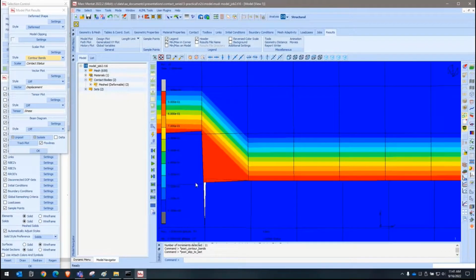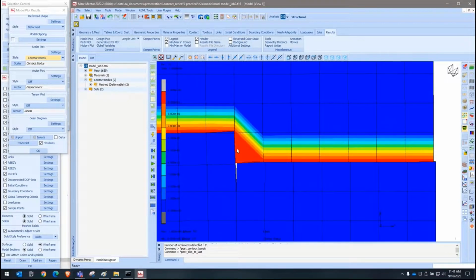The argument is this node is making contact to this face. It is not making contact to that top one. I can only make contact from one node to one face, so this doesn't work. At the top again, the node of the top part is making contact on that long face, but it's not making contact to the top as well. Well, if we make contact from the inside to that outside, that corner there is effectively the same for both of them. So that works better. But from outside to inside, I get really weird behavior at that side.